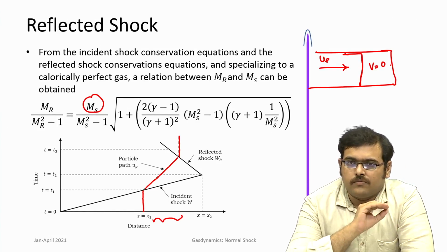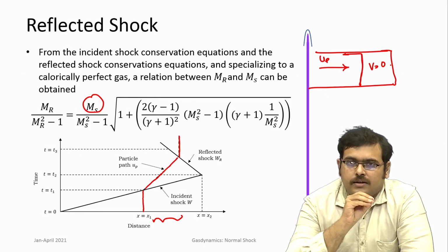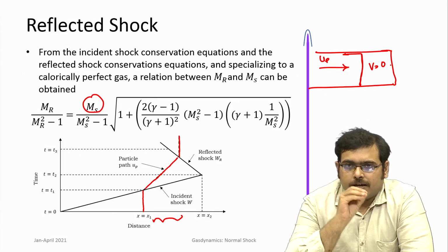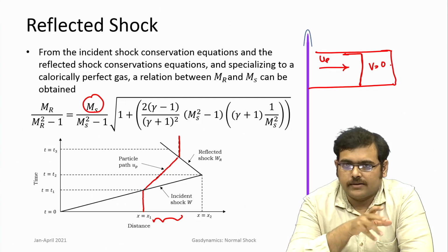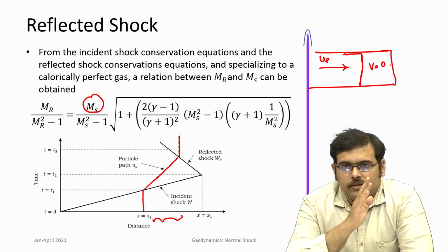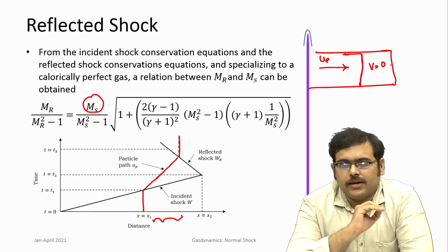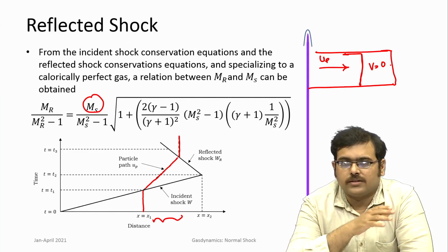Again, when one is looking at the gas motion behind such moving shocks, make sure that the transformations that you apply are correct. So, if you analyze using the stationary normal shock, the Mach number after the shock that you get is relative to the shock wave. So, we should always see that to get the velocity with respect to the fixed laboratory frame, we again use the transformation back.